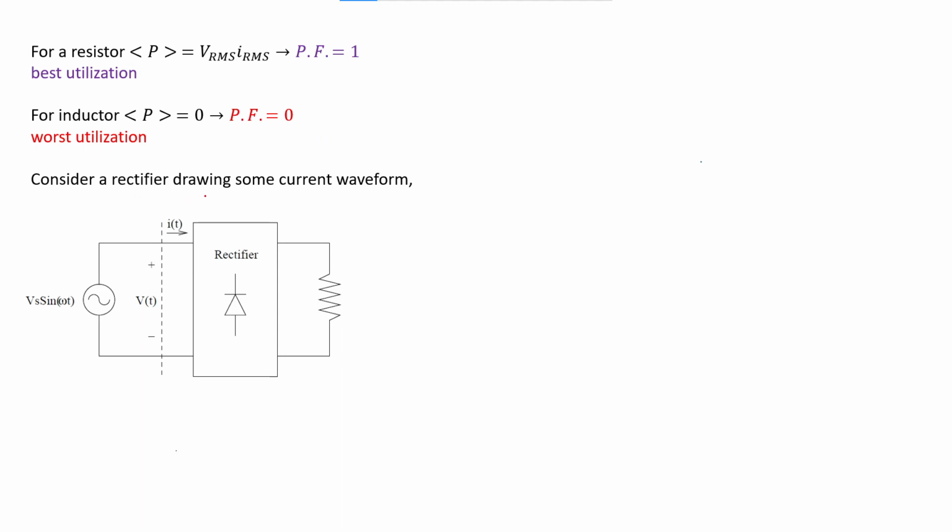All right. Consider a rectifier. Rectifier means you want to convert from AC, here is the AC side, here is the DC side. The DC doesn't have to be straight like this. As long as you have only one side like this, it's DC. But anyway, for operating most loads, resistor load, you want it as straight as possible.